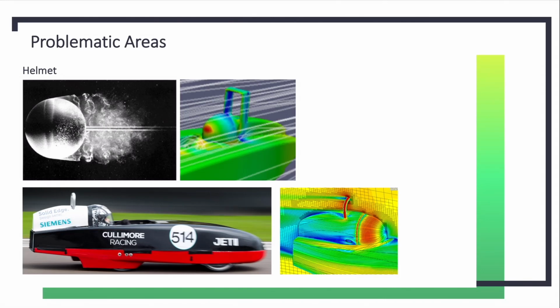and now we're looking at flow velocity, you can see we've got the stagnation point, the point at which the air hits the helmet at the front here. It continues to be attached. There's a little bit of separation in this region here, and you can see a vortex being generated there. But it continues to be attached over the fairing and down into the wake.